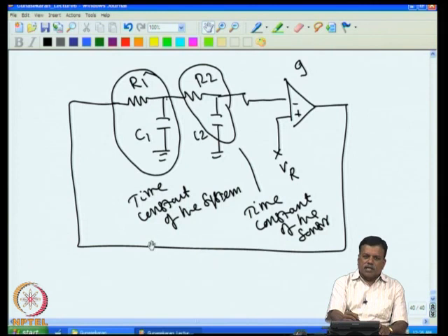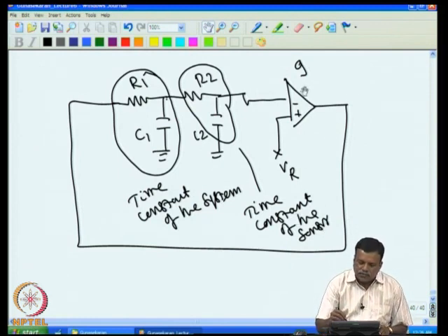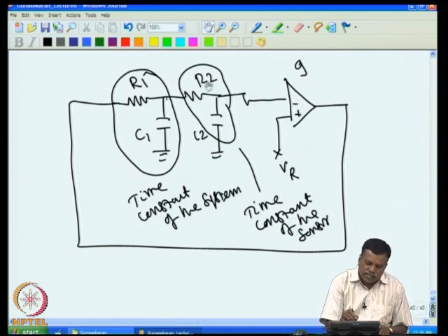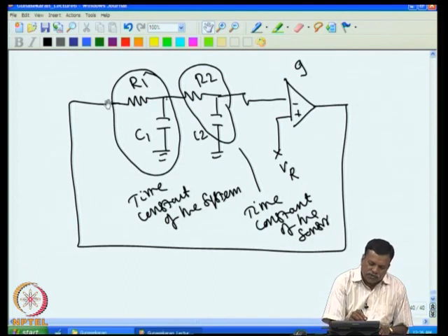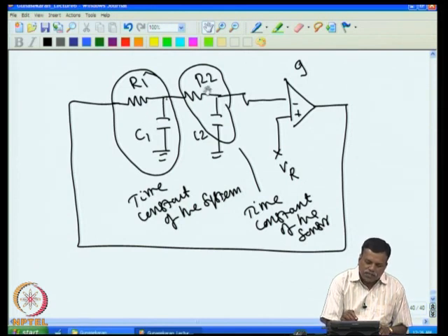That is one condition required for the oscillator to work. So we already produced a 360 degree phase shift. Then another condition to be satisfied for the system to oscillate is that the loop gain should be more than 1. We had given some gain here, but these two are actually acting as attenuators, because if I give an AC signal of some frequency, say 1 volt amplitude, then at this point I will have only a reduced voltage. That means the system works as an attenuator here, and this also works as an attenuator.